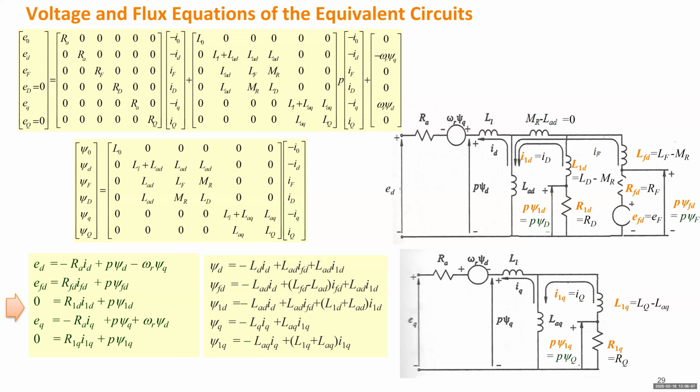So you simply write each equation down using the old notations, and by using those figures, you translate into the new notations. So they will become those 2 sets of equations. And those parameters will be the typical parameters you can see from many generator models, from some software tools from the commercial software vendors.